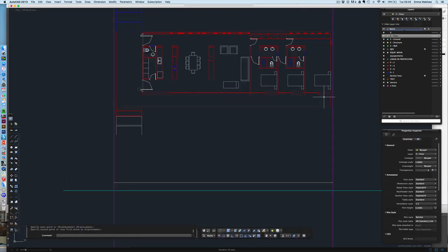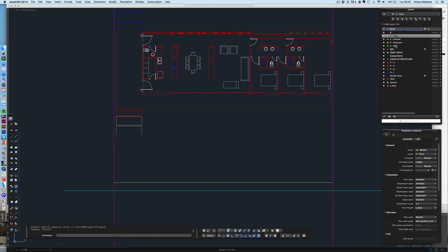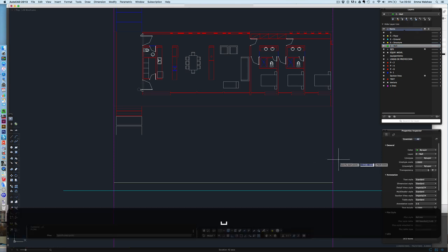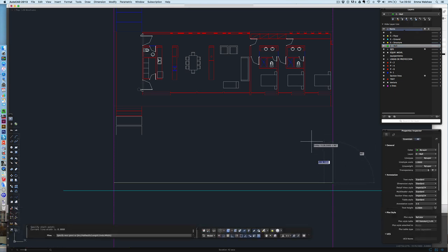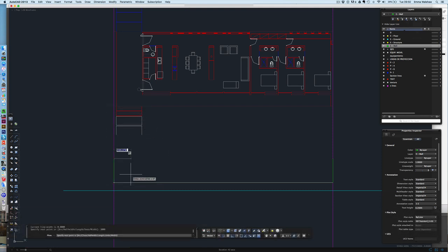Okay, so now let's start looking at the external walls. We can still keep these construction lines because they're still going to be useful for this purpose. So I'm going to select my wall layer, and I'm going to draw my walls, and at the moment I'm going to suggest that these walls are going to be 3 meters high, so I'm going to go 3 meters, and likewise 3 meters. I'm now going to remove these because I don't need those construction lines anymore.